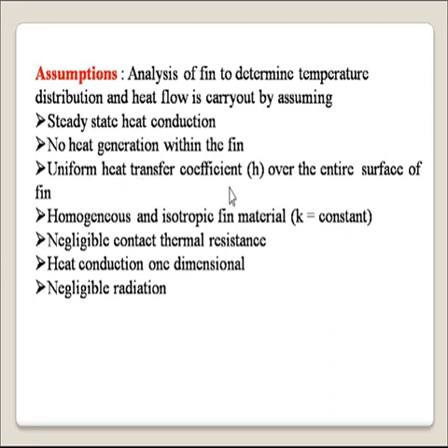Then uniform heat transfer coefficient h over the entire surface of the fin is assumed. Then the material of fin is homogeneous and isotropic, meaning thermal conductivity of material is constant. Then contact thermal resistance between the fin material and the base material is negligible. Heat conduction is one dimensional. Negligible radiation loss, or heat transfer by radiation is negligible.